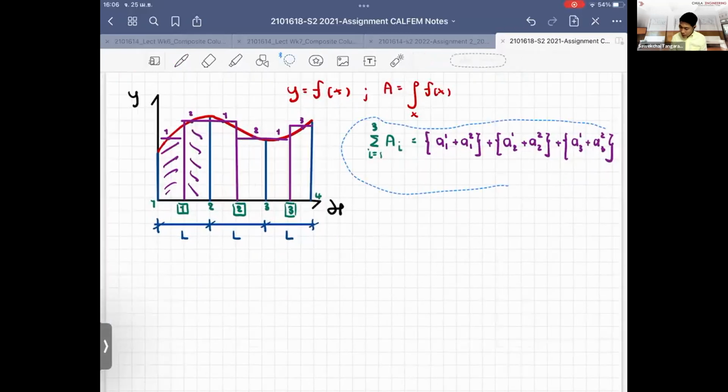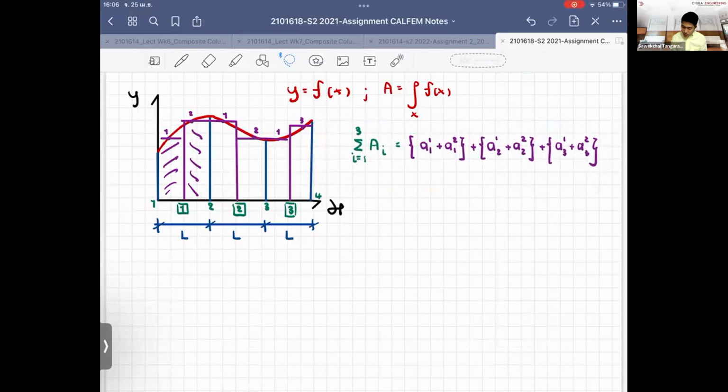By having this type of approximation to get the area underneath the curve, to get more accurate, what you do, you have 2 options. One, put more Gauss points to approximate the curve, or the other, you discretize the structure to be more, right? The more that you subdivide the portion, from 3 to 6, 6 to 12, to 24, you start to get the value closer to what is actually required here, which is the real solution.